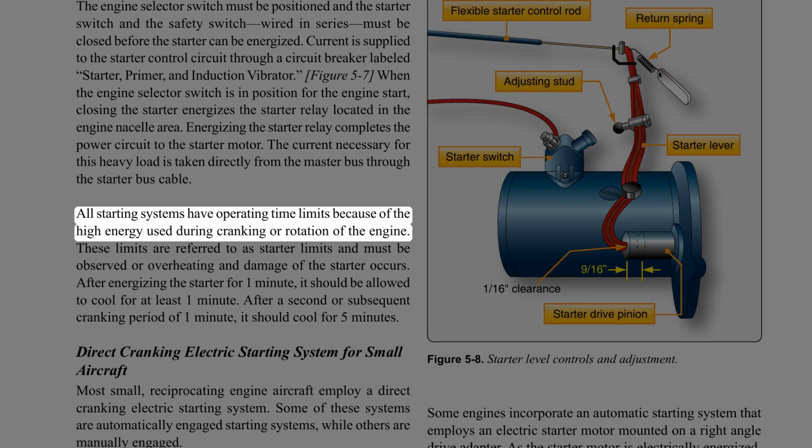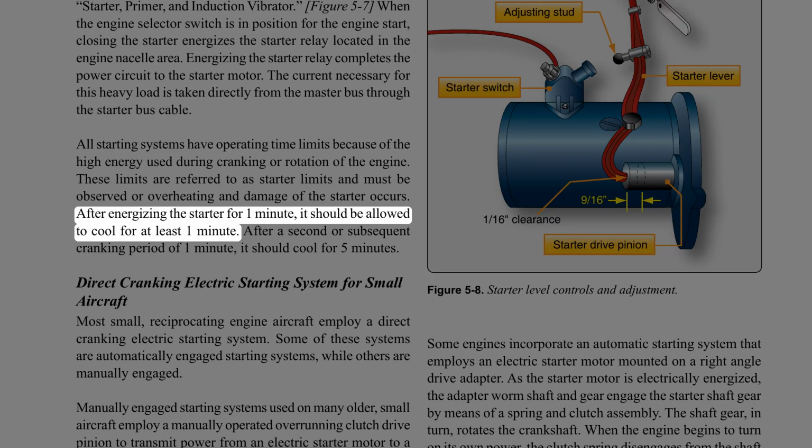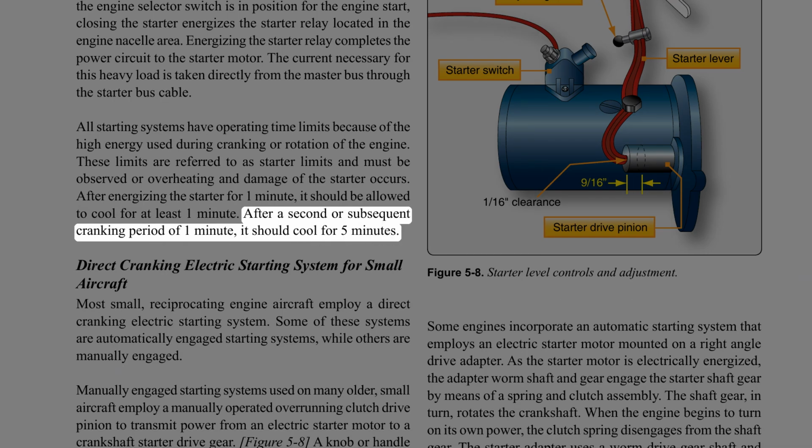All starting systems have operating time limits because of the high energy used during cranking or rotation of the engine. These limits are referred to as starter limits and must be observed, or overheating and damage of the starter occurs. After energizing the starter for 1 minute, it should be allowed to cool for at least 1 minute. After a second or subsequent cranking period of 1 minute, it should cool for 5 minutes.